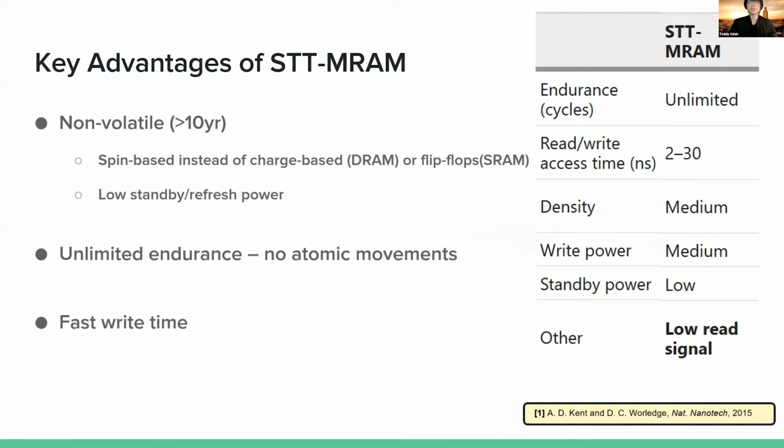And this is because STT-MRAM uses spin-based magnetic storage instead of capacitors in DRAM or flip-flops in SRAM. And what that means is you don't need to refresh your capacitors when they leak, as in the case of DRAM, and you get really low standby power.